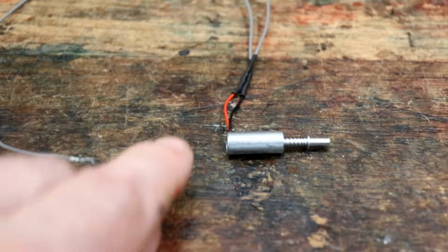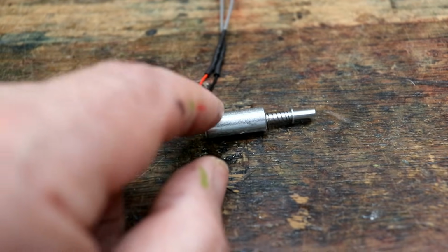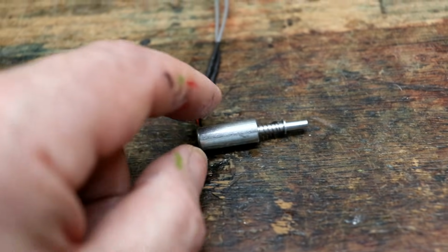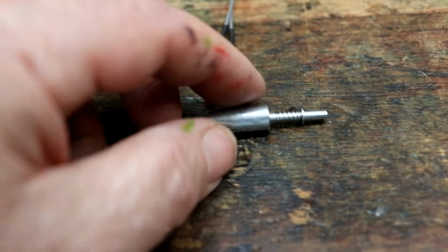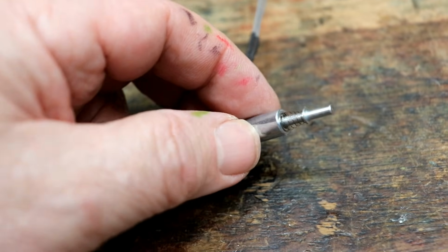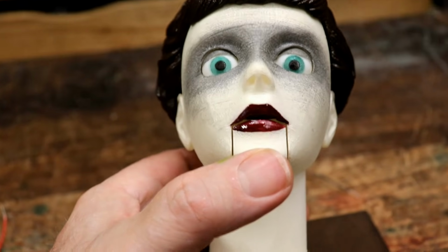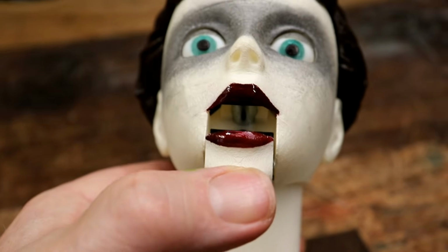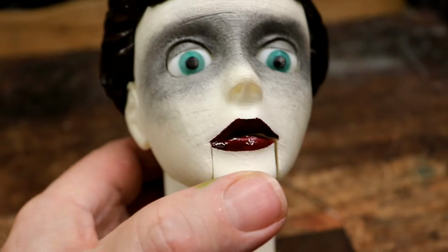The other thing to notice about these small solenoids is they do get warm. Just having that switching on and off, a second on, second off, so a 50% duty cycle, after just a couple of minutes that was getting warm. And I've realised that's why they've got such a heavy metal outer piece, because it's a heat sink for it. They're small, so having half an amp going through that is going to create quite a lot of heat. So the moral of that story is don't have her sitting there with her mouth open catching flies. However, I did design her so that the solenoid just sits in the open inside her mouth, so there's going to be quite a lot of airflow through there and out the back of her head.